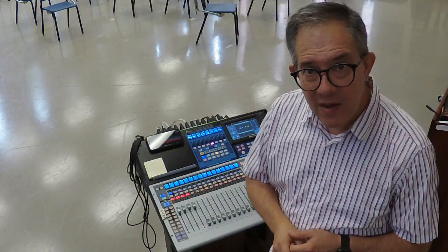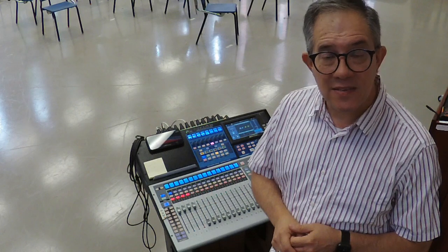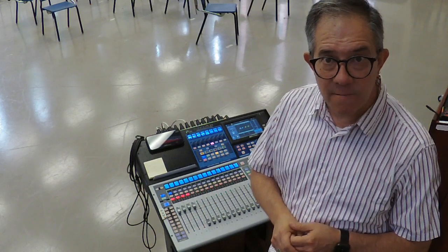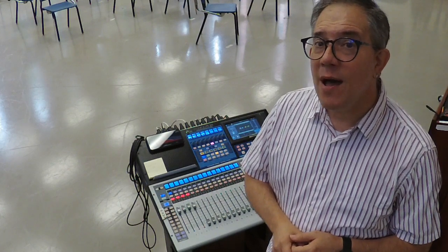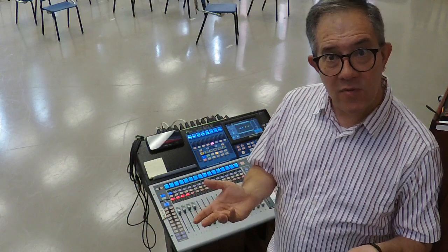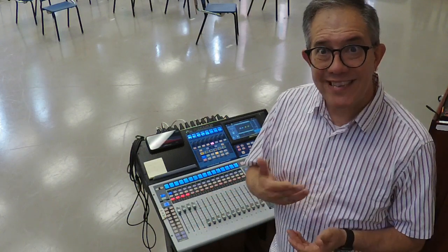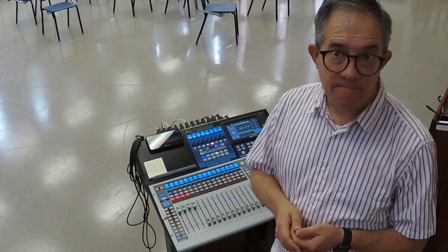If your speaker system, either because of EQ you've applied to it or because of the tendencies of that speaker system, also emphasizes 400 hertz, then you will have problems, because the microphone system and the speaker system are both emphasizing a frequency, which will tend to make it roll and ring, which causes problems.